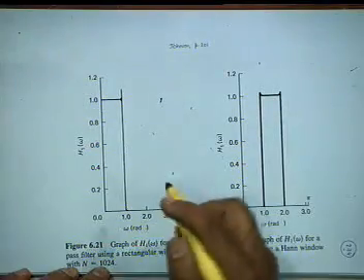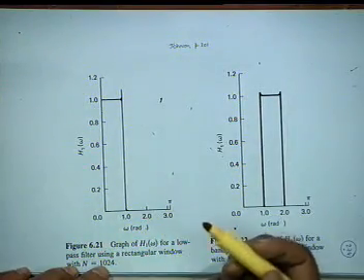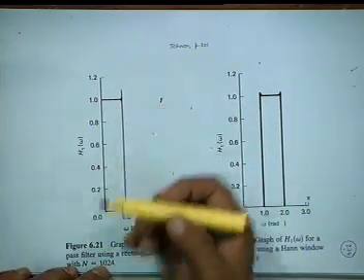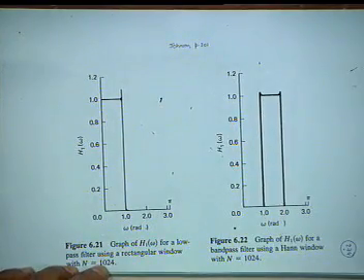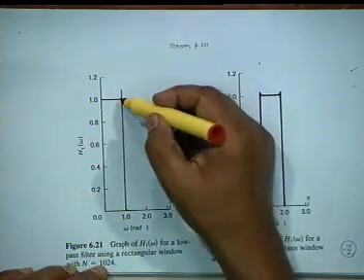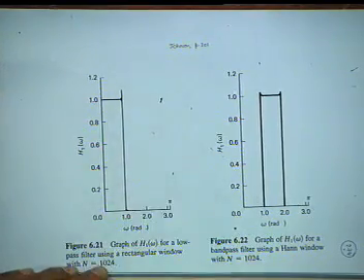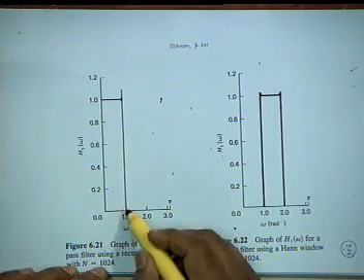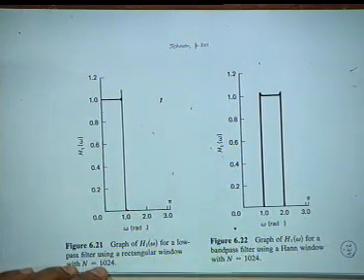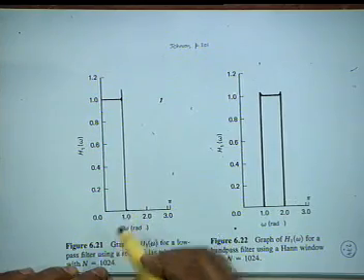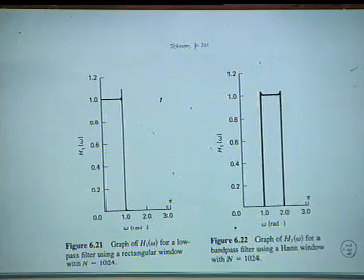So 1024, and you see the rectangular window. You see there are no ripples. You can't see any of them. But this rod still remains, and it is approximately the same, 17.8%. This is what Gibbs phenomenon is. Similarly, here also it has not been shown, but here also there is a decrease. There is a mistake here.